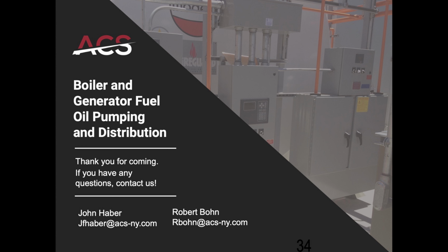Next one, can a single number 2 oil storage tank in New York City be used to supply fuel to a boiler as well as an emergency generator? It can. It's not recommended to have both a generator system and a boiler system on the same loop, because let's say hypothetically you're running your boilers, need those boilers to stay on, but then your emergency generator has to kick on.